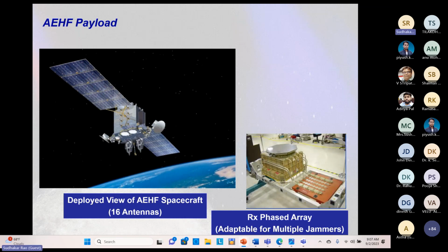This is the phased array on the right, you see. It has about 400 horn elements. On the top is the thermal cover, which is important to minimize the temperature variations across the aperture. Then you have the down converter, and then you can see the heat pipes. The heat pipes go down, and on the radiator panel it dissipates. So you convert into a higher frequency, which is C-band, and then you down convert directly after that to the digital payload. All the phase shifting, amplitude tapering, everything is done through variable phase shifters and attenuators at the digital level, and the combining as well. It produces about 8 beams of different shapes, spot beams or area beams, because you can adapt the beam to any requirements we have.